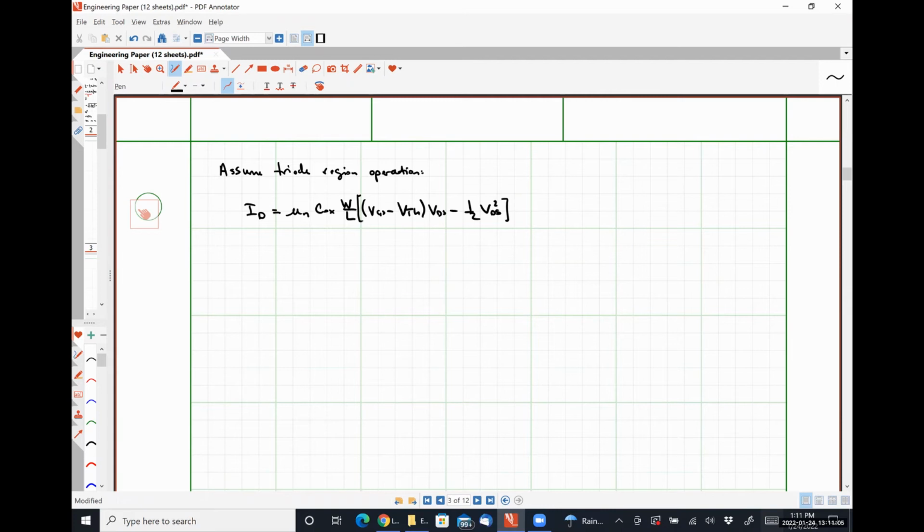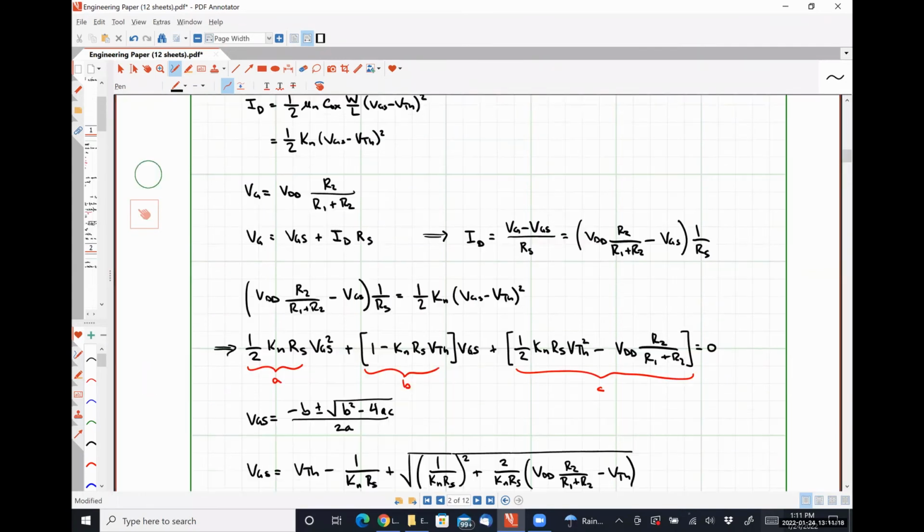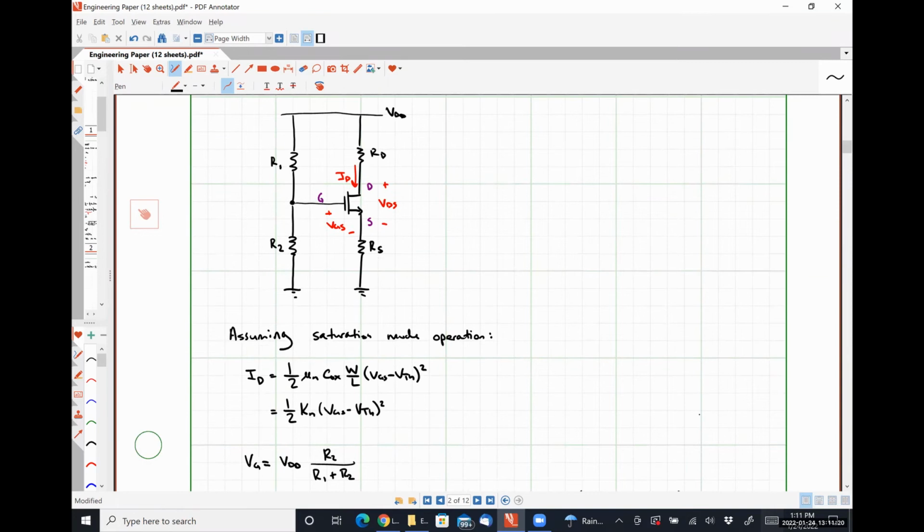So we can see, doing KVL around that bottom loop, VGS is equal to VG minus ID times RS. I'm just going to scroll up here so we can see that, prove it pretty easily. So we said that VG was equal to VGS plus ID RS. So it stands to reason that then VGS is VG minus ID RS, which is just what I said.